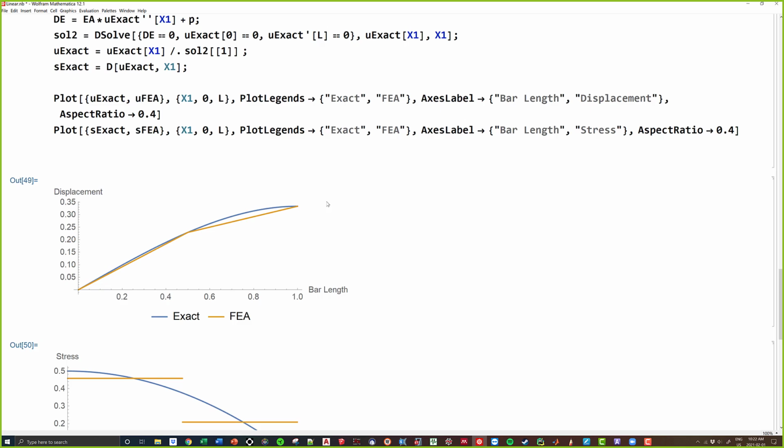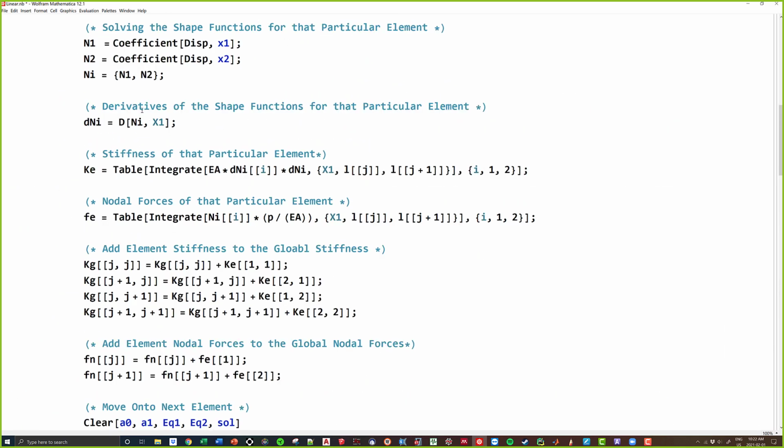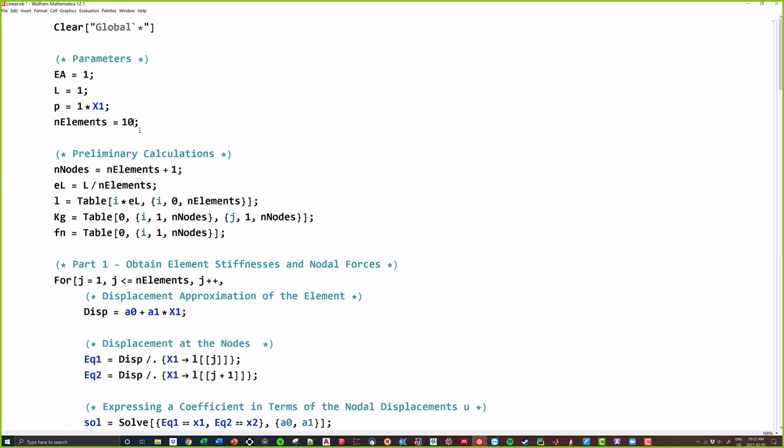The only reason why this is the case is because our exact solution is a polynomial. As we're going to see later on, most of the time our exact solution will not be a polynomial. So what we're going to see is at the nodes, it'll still be very, very close to that exact solution, but exactly the same, probably not. The thing to keep in mind here, and this is all I'm trying to show you guys, is when we're dealing with this FEA, we make sure that our displacements at the nodes are very, very good compared to the actual solution. It's what happens between the nodes, aka the element, that we start seeing the error. How do we decrease that error? Well, one of the solutions, as we saw, we can say, well, instead of 2 elements, let's have 10 elements.